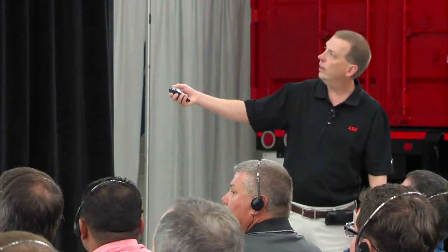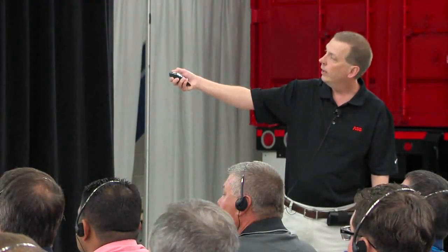DC hold means the motor's ramping down here, we told it to stop, it ramps down to this DC hold point, and then it just injects DC out there. So the motor will hold at that frequency. Then if we're ready to run again, when we issue our run command, it'll stop the DC injection and go right on out and run again. So it will output DC to the motor whenever you're not commanding a speed.